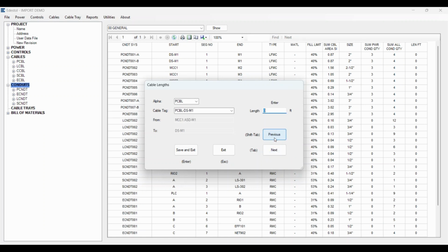It also gives you some information on what each cable actually is. You've got P cable CPT, which runs from the MCC1 circuit breaker CPT to CPT. This is the transformer sitting beside the MCC, fed from a breaker within the MCC. This is a cable, so let's give it about 12 feet. The next one is in the list; it just goes down your list over here.